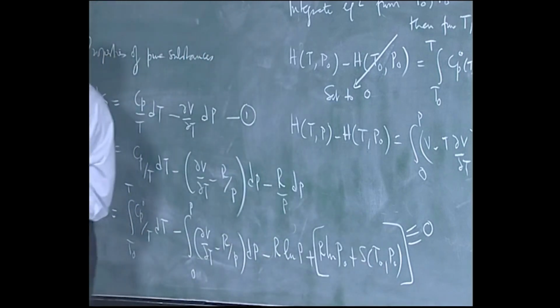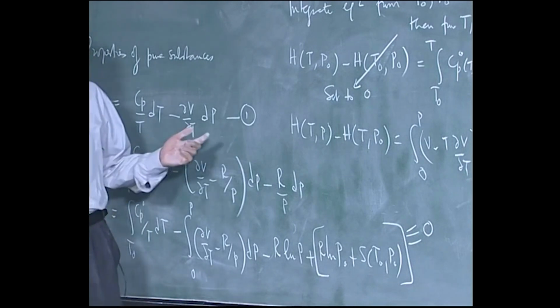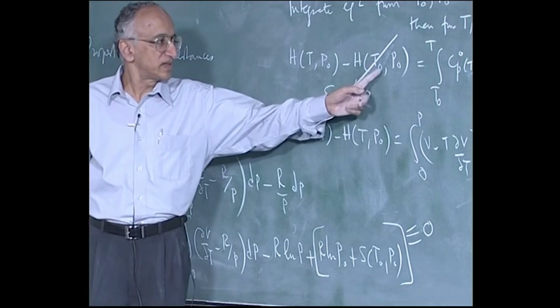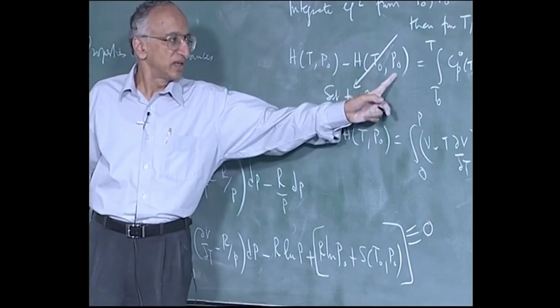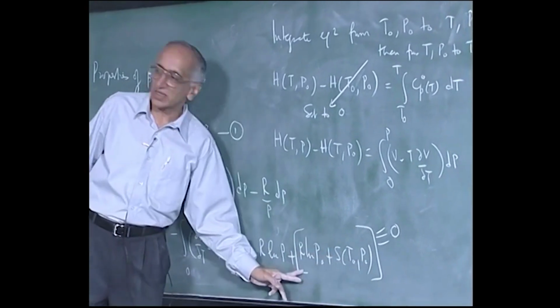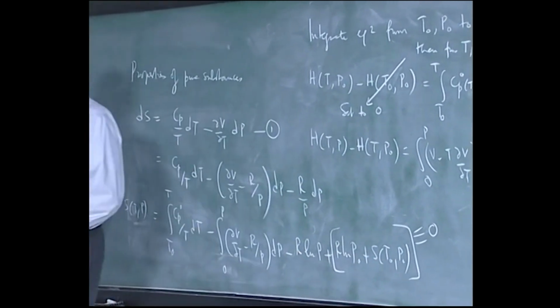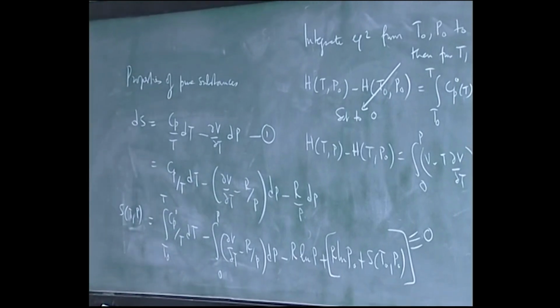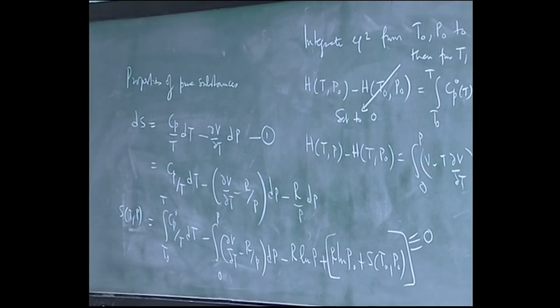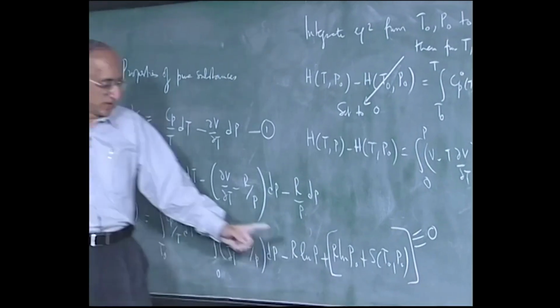Is this clear? So on top of every chart there will be a chart that gives you thermodynamic properties or tables. It will say H at T0 equal to 0, S at T0 plus R log P0 equal to 0. So they will not write S at T0 is equal to 0, and it does not matter because it is the same minus infinity that you are subtracting.